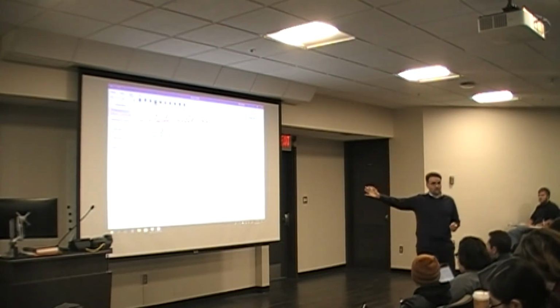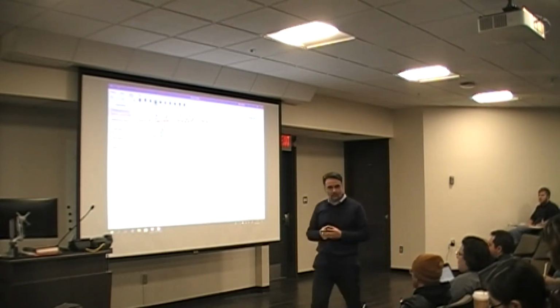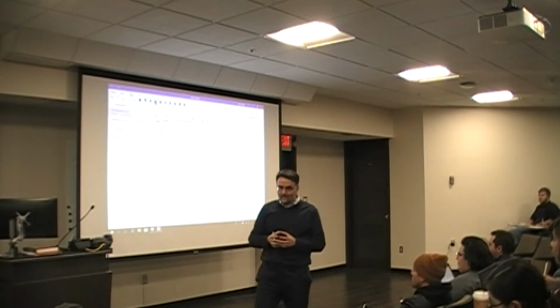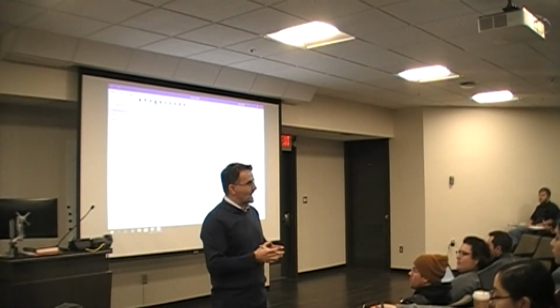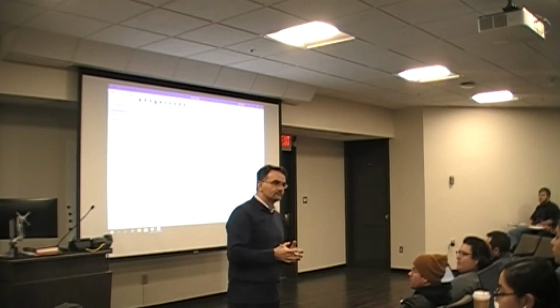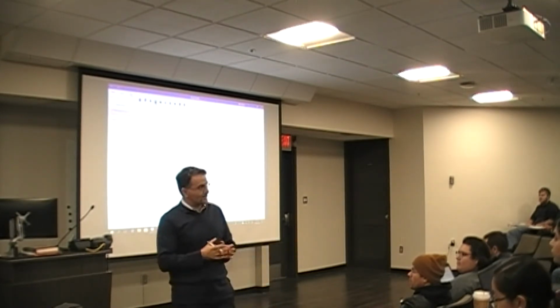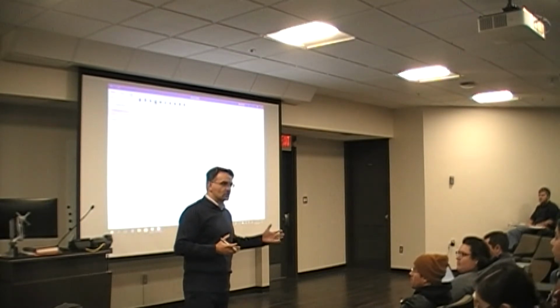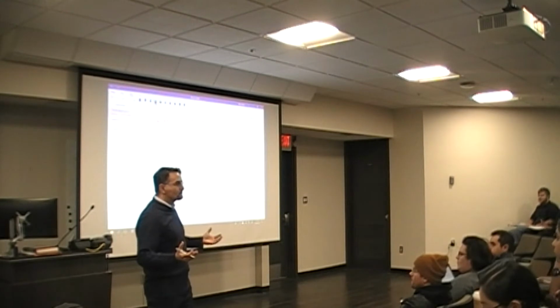Now, for this specific case, since we are looking at uniformly graded material, you're looking at big, huge chunks that create big, huge gaps in between. What can you tell me in terms of the diameter of those tubes? They are much wider, right? So wider tubes, how can you correlate that to the permeability of the soil? Extremely permeable soil, right?